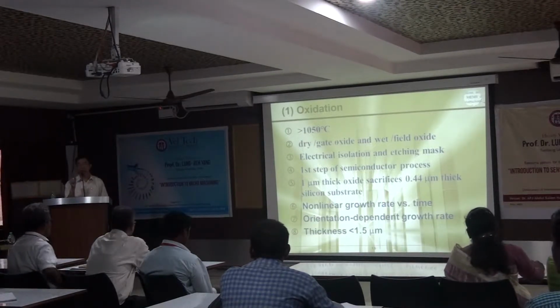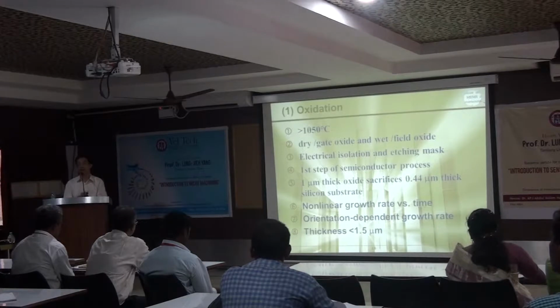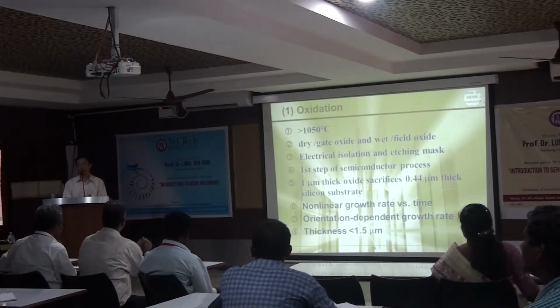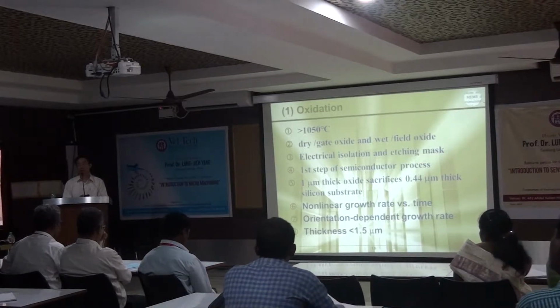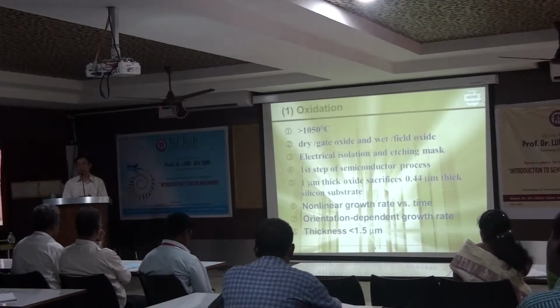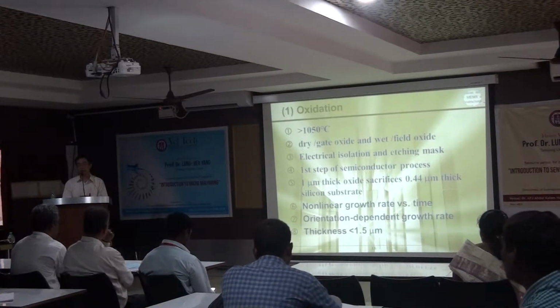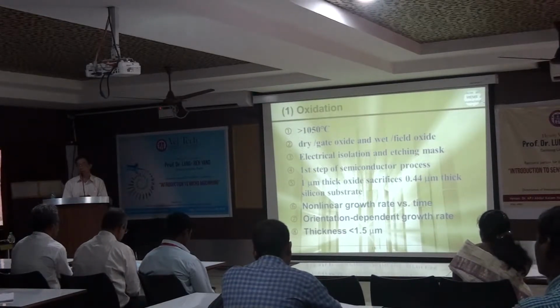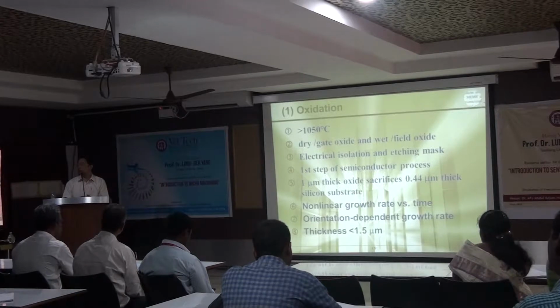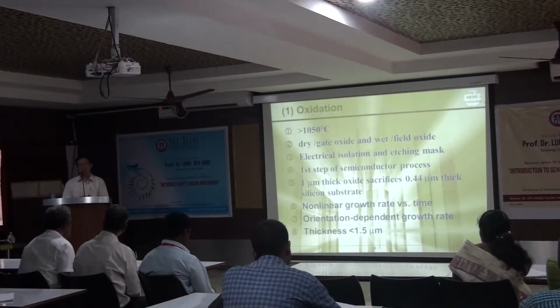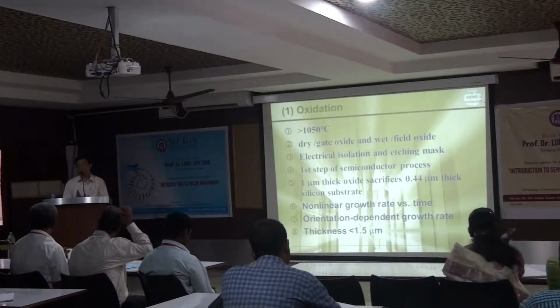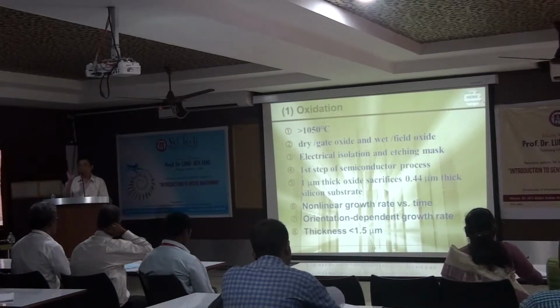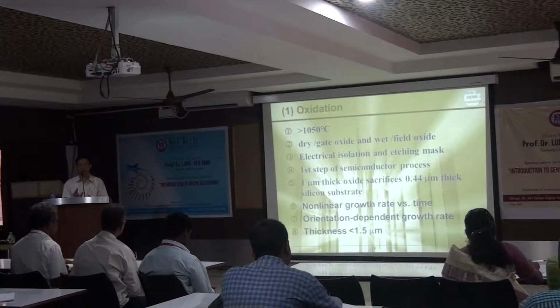Even at room temperature, because oxygen is very chemically reactive, it's very easy to touch your silicon surface and oxidize it, even under an ambient temperature of 35 degrees C. The native oxide is not very thick, maybe only several nanometers, very, very thin. You can even ignore it.